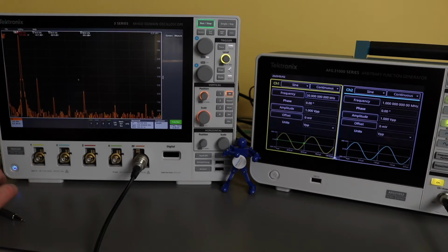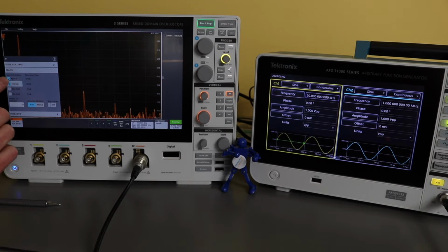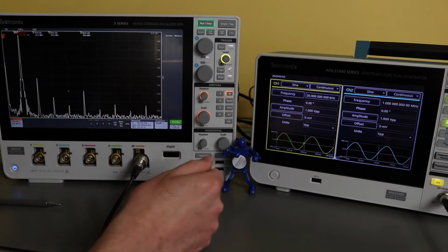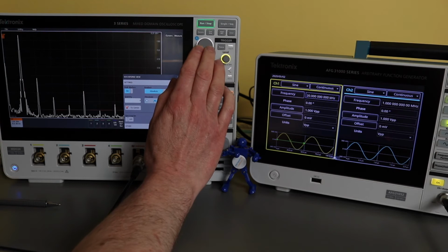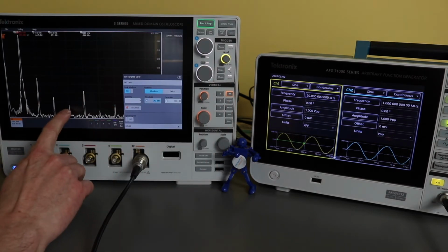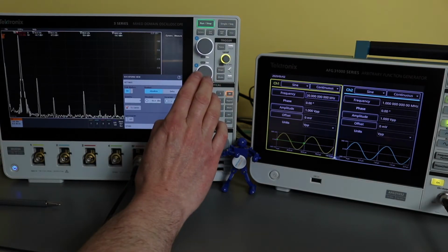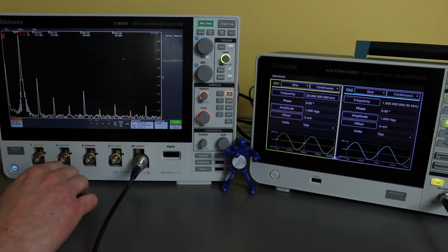And you can see I'm having trouble picking up some of these peaks that are here. I can change this to averaging. And that gives me a little bit steadier. But even if I change these, the level down here, I'd be expecting this peak to be picked up, but it doesn't. So I've picked up 140 kHz now.